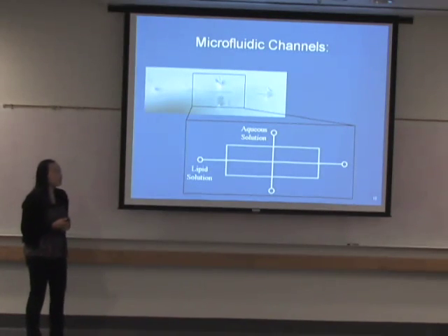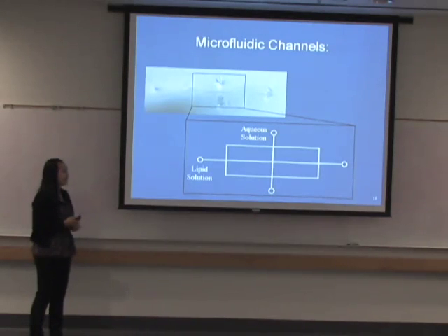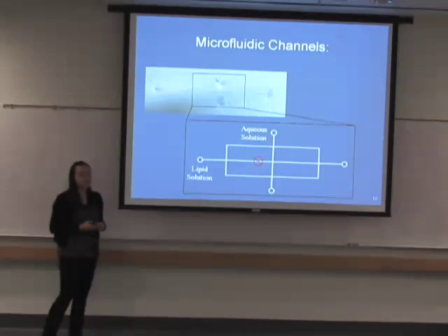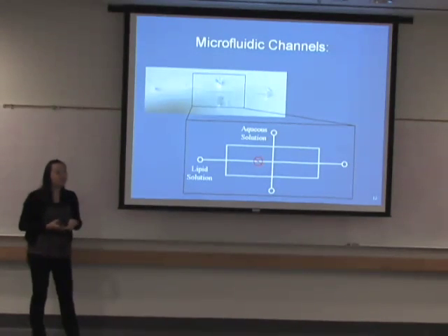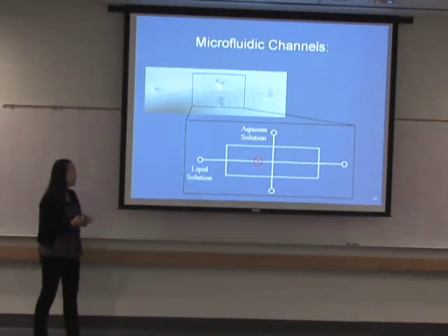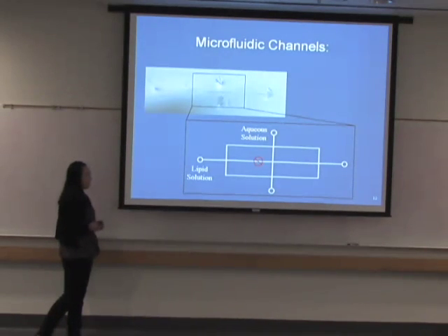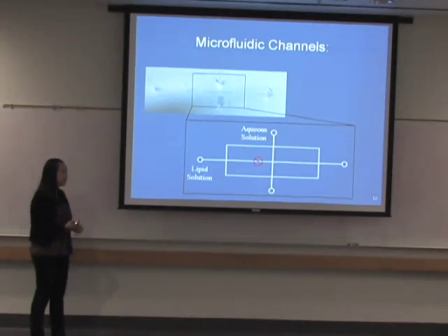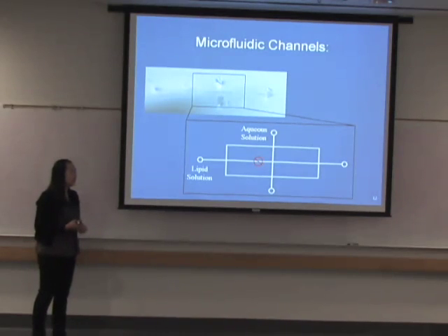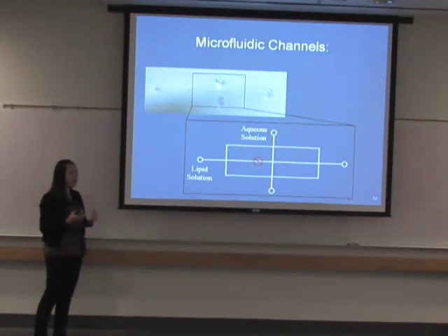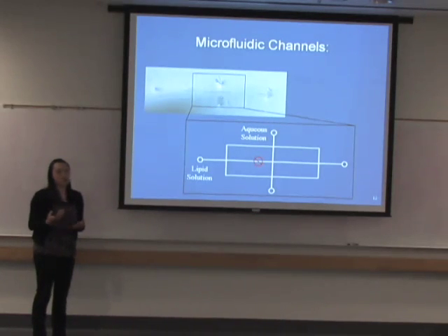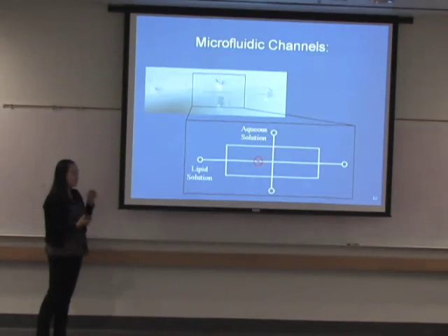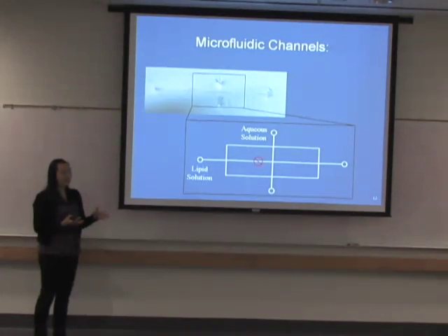So we were working on this, and then we kind of caught ourselves in a dilemma in which our lipid solution actually reacts with the PDMS material we use to make our channels, which caused a deformation in our material and actually collapsed our channel right there. And that completely cuts off fluid flow and prevents us from forming our membranes. And so as of now, we are still in the process of working on a new solution that, when heated to a really high temperature, will form almost a glass layer between the solution that we're going to be using and the PDMS material.